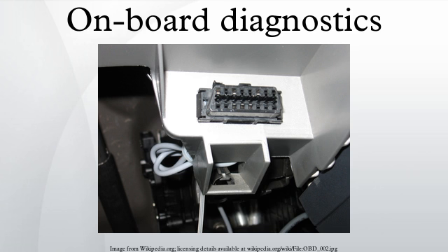1991, the California Air Resources Board requires that all new vehicles sold in California in 1991 and newer vehicles have some basic OBD capability. These requirements are generally referred to as OBDI, though this name is not applied until the introduction of OBDII. The data link connector and its position are not standardized, nor is the data protocol.